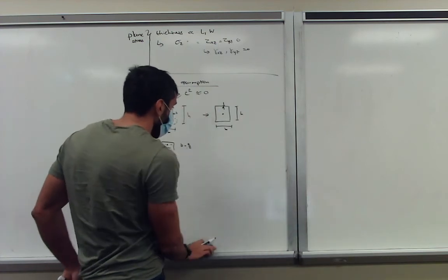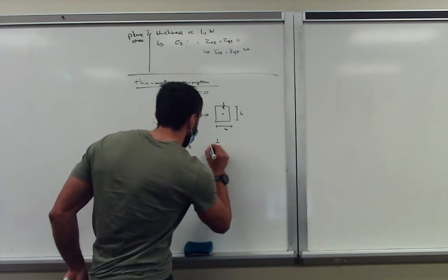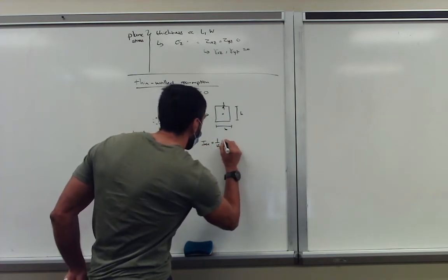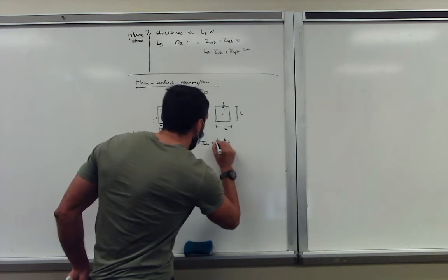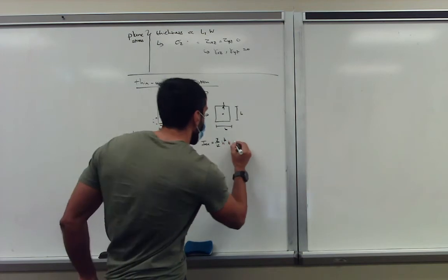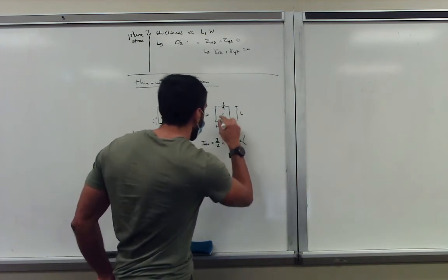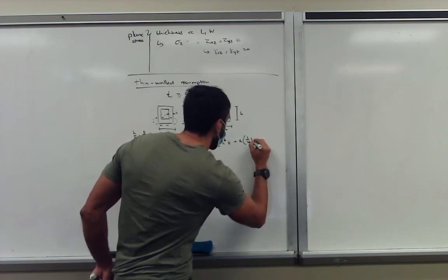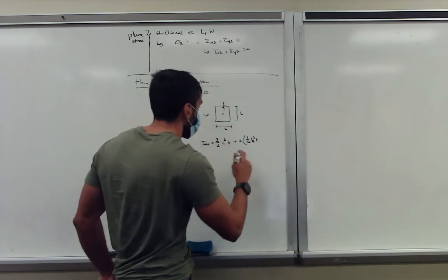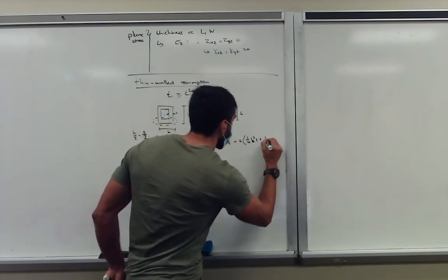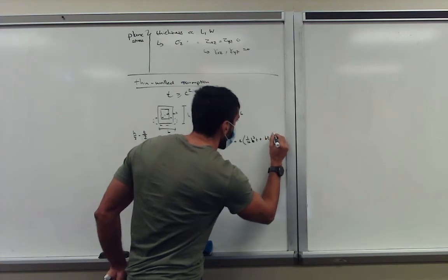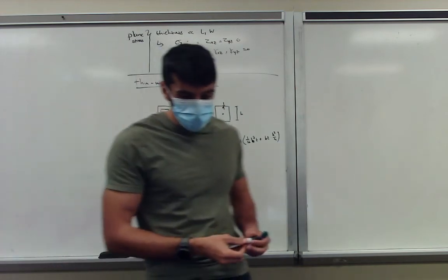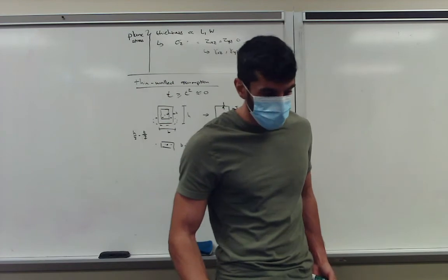So if you then just do the moment of inertia, you can say Ixx of the cross section is equal to 1/12 multiplied by h to the power 3 times t times 2, so 2 over 12, plus twice the contribution of these two top and bottom, which is 1 over 12 b cubed t, because the height is equal to thickness, plus the A d squared term, so that's b times t multiplied by h squared over 4. So it simplifies the equation. Good.